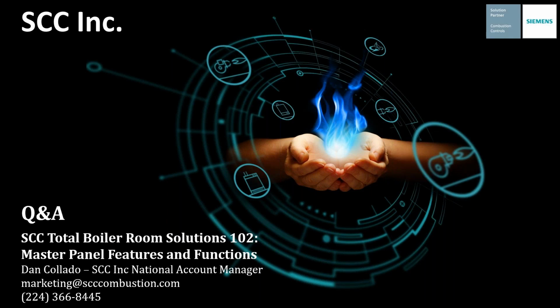I'd love to be able to say that our panels can handle 100 million volts of electricity, but unfortunately, that's not the case. Fortunately, all the Siemens LMV series controls and all of our RWF55 controls have a dedicated watchdog timer. All of our products are slave devices when it comes to Modbus communication. So this timer specifies the amount of time allowed with no Modbus communication from the master panel until the LMV or RWF controllers revert back to local pressure or temperature control based on a local set point.